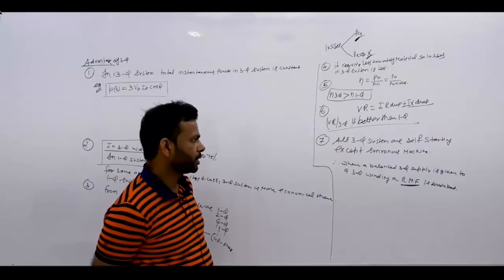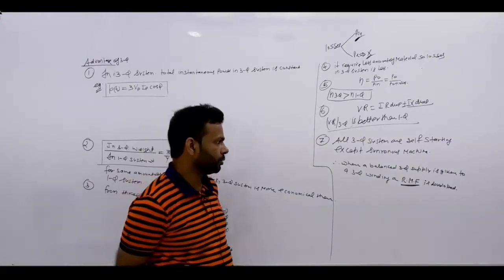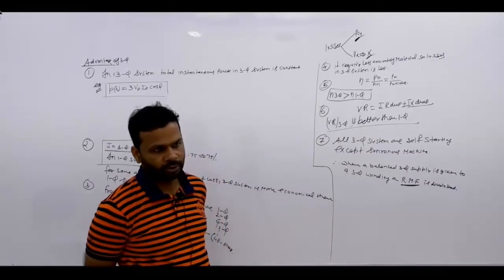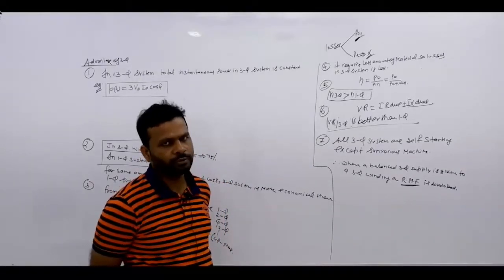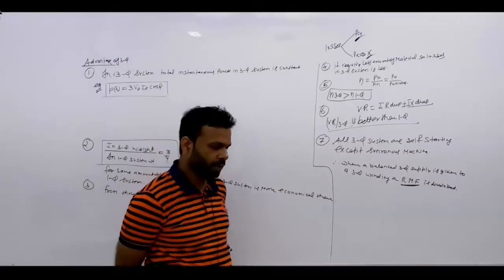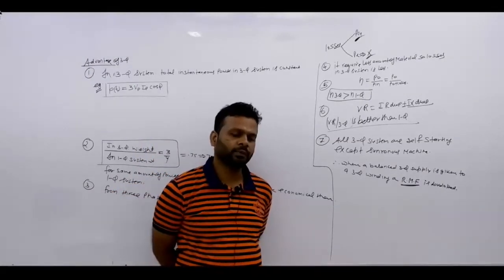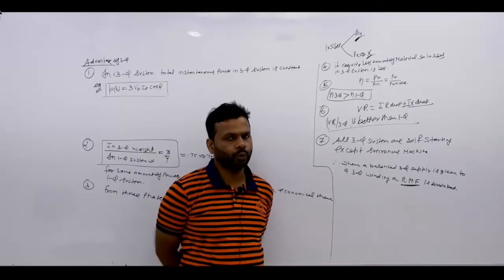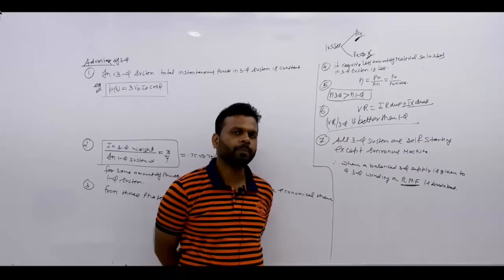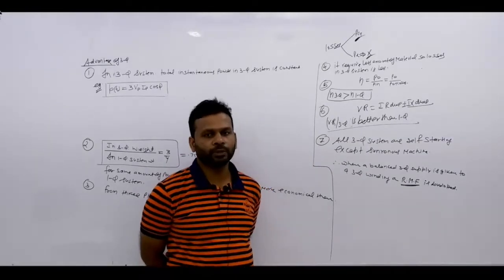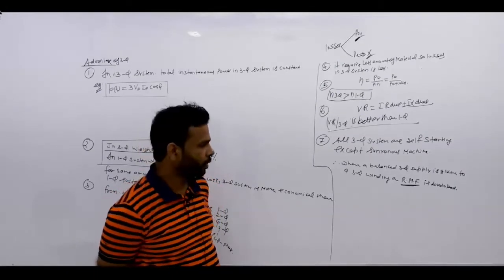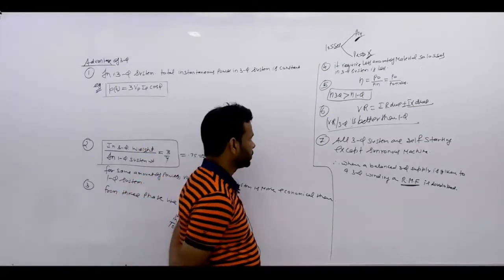So three-phase systems are self-starting except the synchronous machine, because in a three-phase system we have the rotating magnetic field, but in a single-phase system we don't. Again we have a pulsating magnetic field, and that pulsating magnetic field is resolved into two parts. One is moving in the forward direction and the other in the backward direction with the same speed. So the resultant magnetic field is zero, or the force is zero. So this is the 7th point.